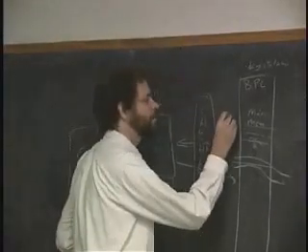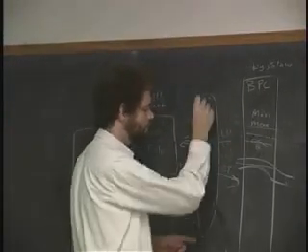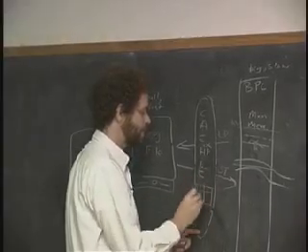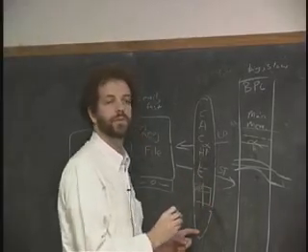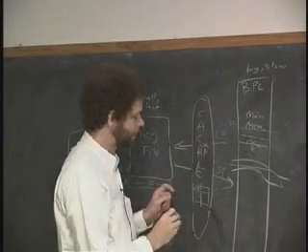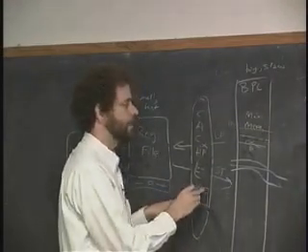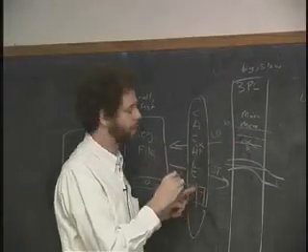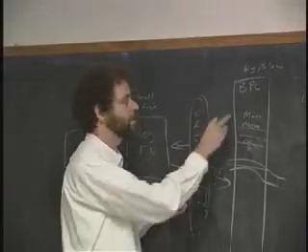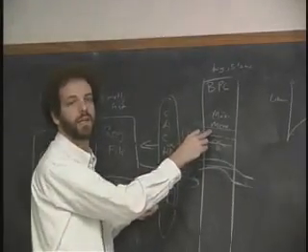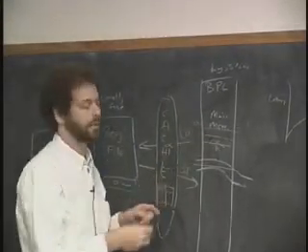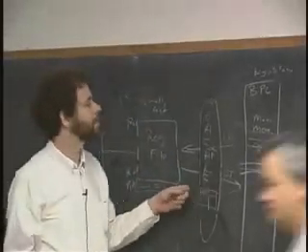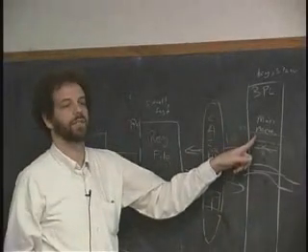It will start a read from location 100, and it'll search through the cache for a table entry whose address tag says, I have the data for location 100 in here, looking for the data, and whichever one gets it first, it will abort the other one. In particular, if it gets a hit here, it'll stop doing the memory lookup here and then go on to the next thing. Okay, and that means that reads, when they hit, only take this length of time, and when they miss, they only take that length of time.